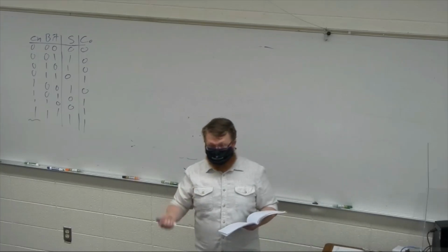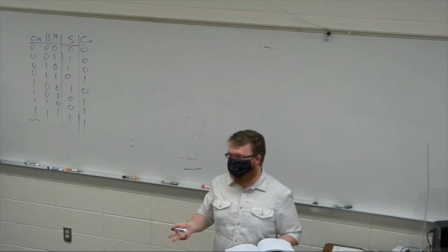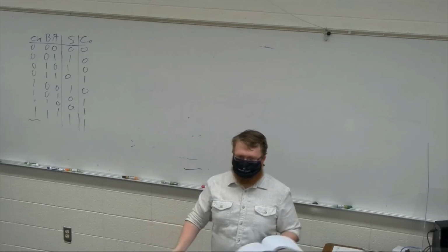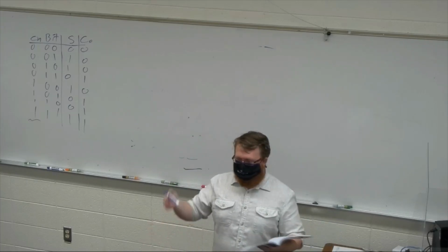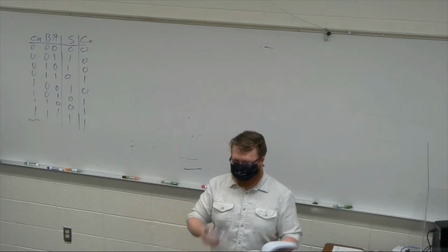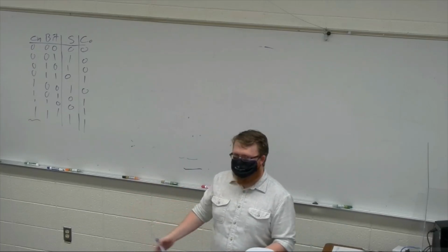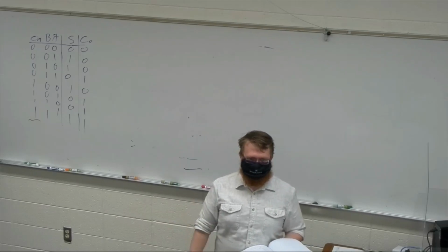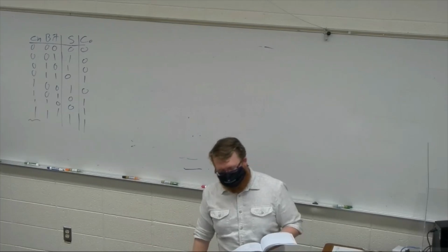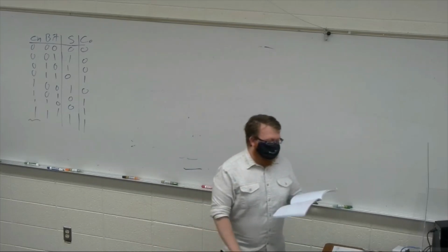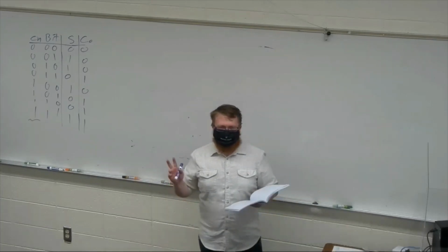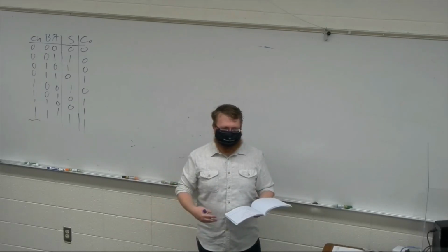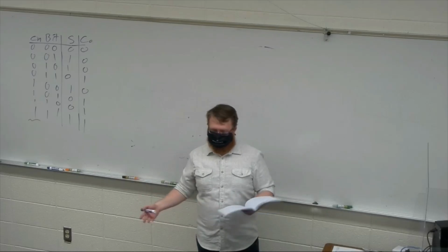If you need really, really fast, you can use a ROM, right? You can just put all possible values of the multiplication for every bit you have, and then it's just look it up. Here's my input. What is my answer? This has the benefit of being very fast, right? It's one clock cycle and you have your answer. Again, these scale horribly. They're huge. The last one is what we would call hard multipliers. These are ones that are built into the fabric of the FPGA, and you would access this using an IP core.